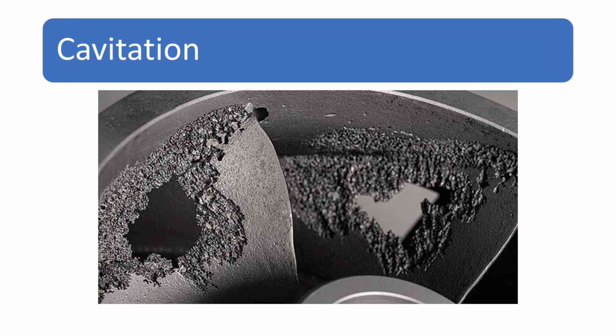So, for example, water at 10 degrees Celsius will flash into vapor and foam bubbles at locations such as the tip regions of impellers or suction side of a pump, where the pressure drops below 1.23 kilopascal.